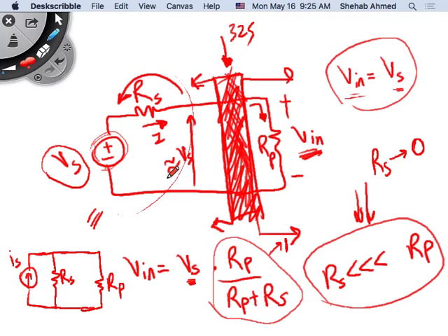I can have another sensor that is a capacitive based sensor, right? So maybe the capacitance is changing. If the capacitance changes, the value of capacitance will limit the amount of charge on the capacitor, for example. If you have a certain voltage limit for that capacitor, a corresponding charge will be allowed to be deposited on the plate of the capacitor. Changes in charge will correspond to changes in current, right? So I can represent that sensor as a current sensor, for example, and I can move from Thevenin equivalent to Norton equivalent easily, right? We know that from 214.